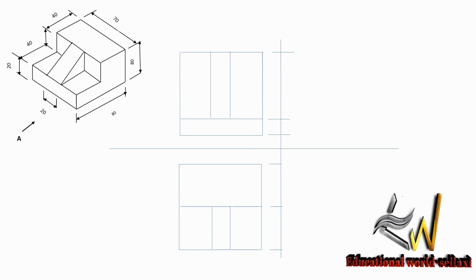And from there, using our 45 degrees set square and our ruler, we project lines at 45 degrees from the plan to the side, and after that we erect perpendicular lines with the help of our ruler and set square as well.